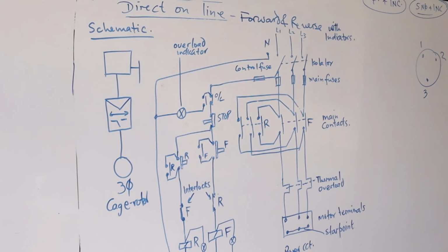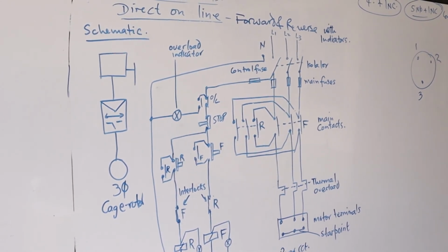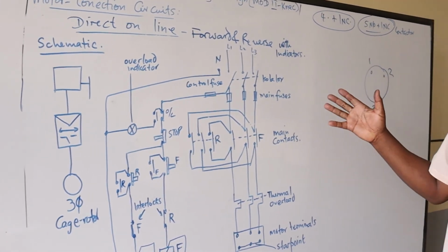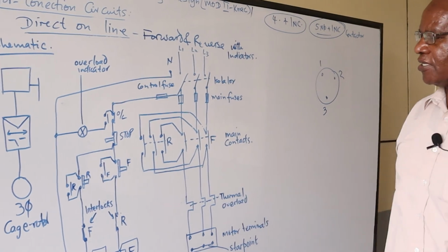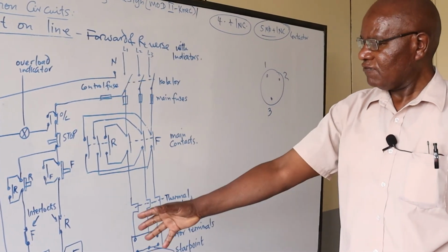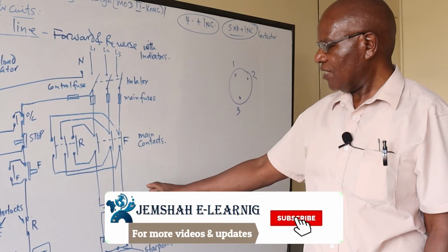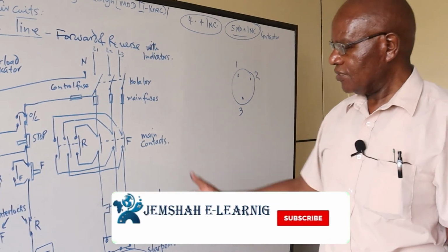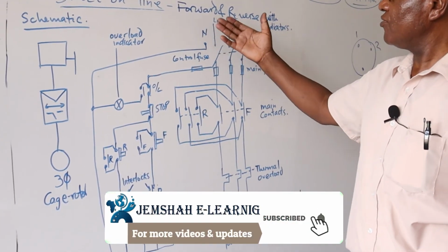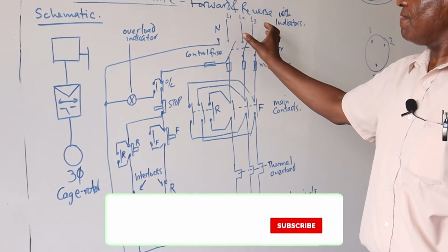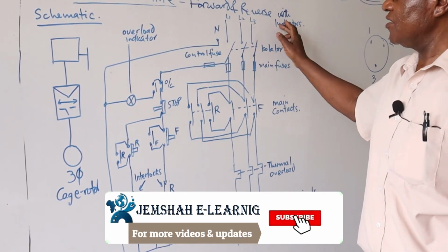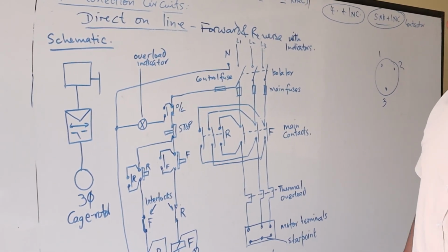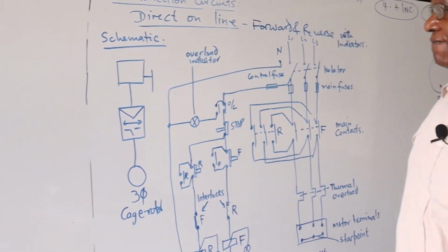So our next circuit will be star delta, which again we will do as the schematic as well as the power circuit and the control circuit. Again, control circuit, less currents flowing. Power circuit, where you have got the heavy currents. Thermal overload, you can set at what current you want it to trip. And as I said, the contactors, you can decide whether they operate on 240 or 415. With 415, I said the connection will be slightly different. You connect this one to another phase, and you connect a control fuse. And that is our schematic.